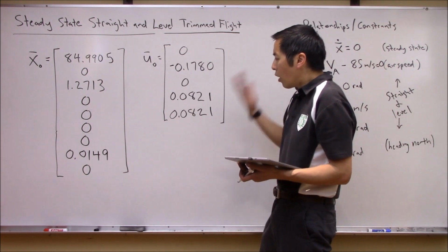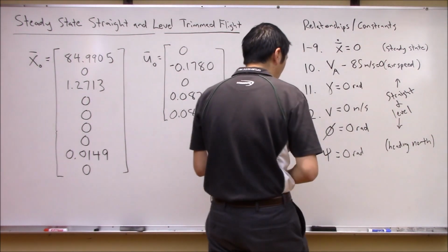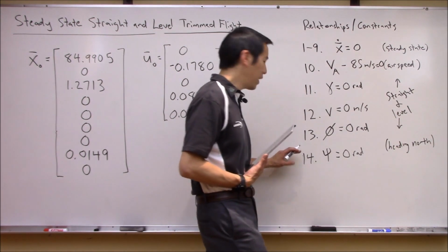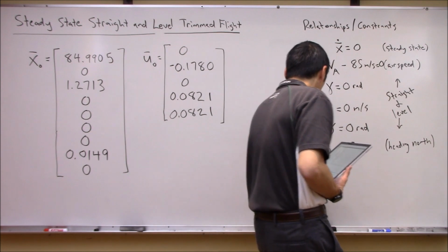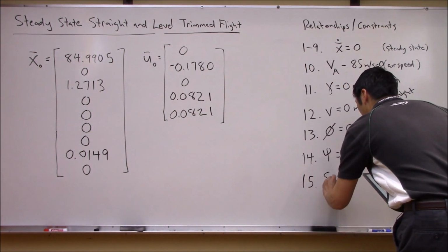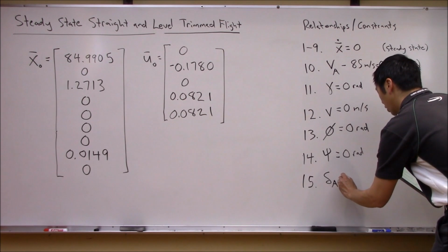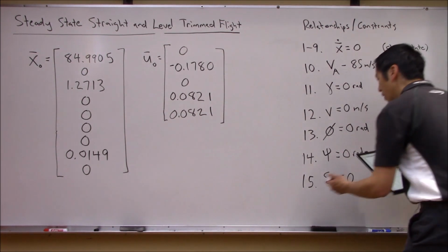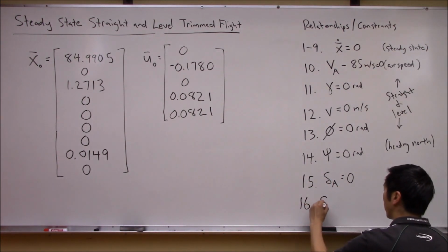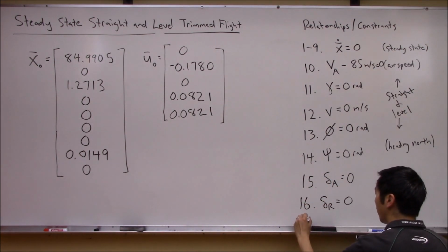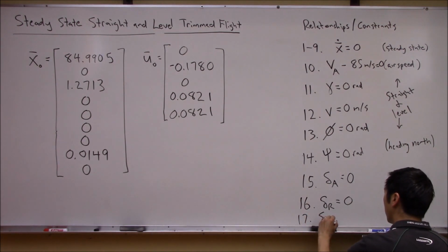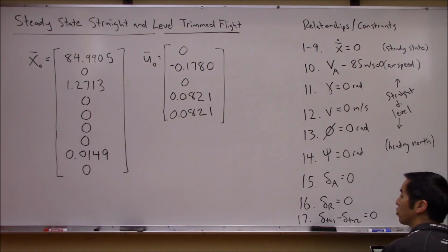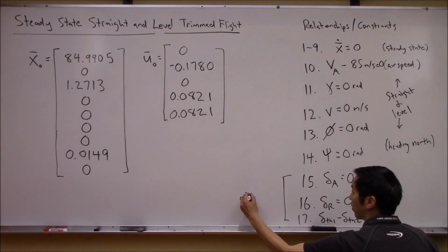Now, one thing that I've seen in the past is a lot of people have asked, why didn't you just add that constraint a priori? Like you knew ahead of time, right? Why didn't we just say over here, I can put the aileron as part of the penalty function, as part of our constraints, right? You intuitively know that there should not be any ailerons. And same thing, why not add that the rudder should be equal to 0, and then maybe even say that the throttle 1 minus throttle 2 has got to be equal to 0. Basically saying that the throttles have to be matched. So you could add these constraints.